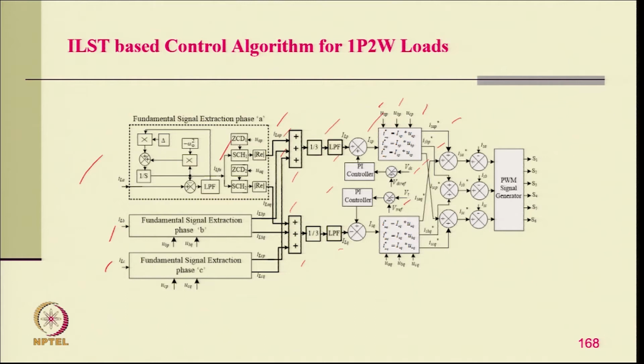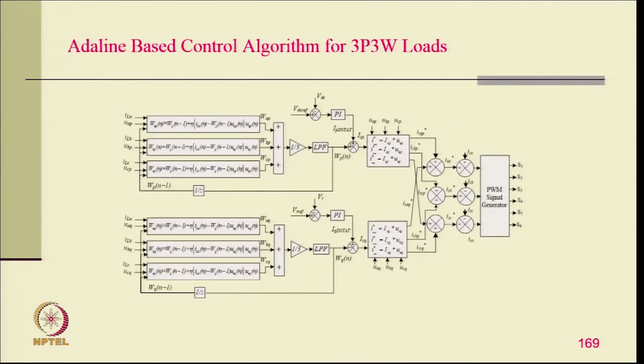These are typical DC quantities, and they work very well. Then we subtract it from the load, because the load reactive power has to be supplied locally by the DSTATCOM; only a small amount of reactive component has to flow through the generator side. This amplitude is multiplied by the quadrature template, which is at 90 degrees leading the voltage. This gives the quadrature component, and then we add both. This gives you a reference 3 phase generator current; we have the feedback generator current, and we put a current controller for generating the gating pulses. So, it regulates and provides load balancing, harmonic elimination and voltage control at the PCC.